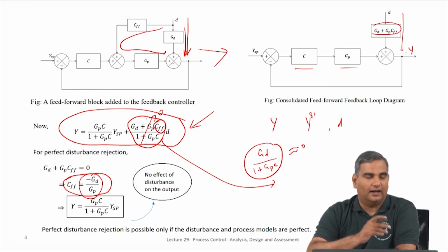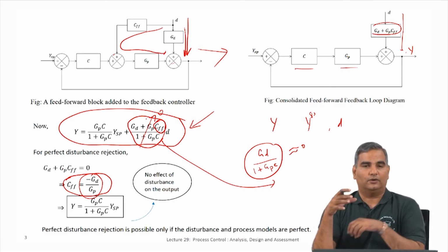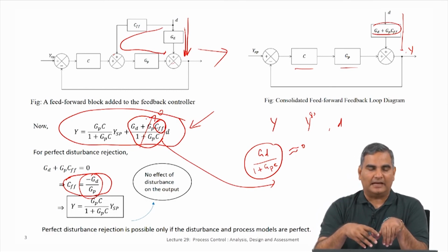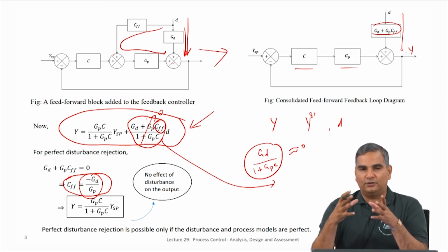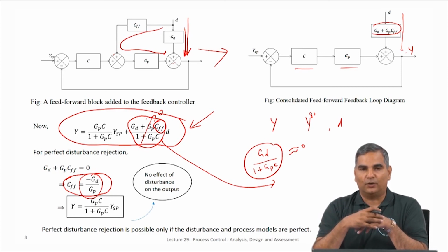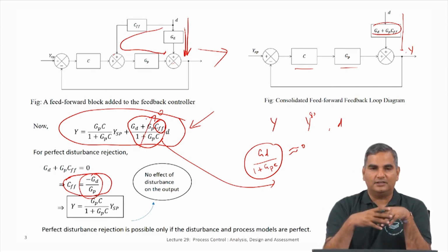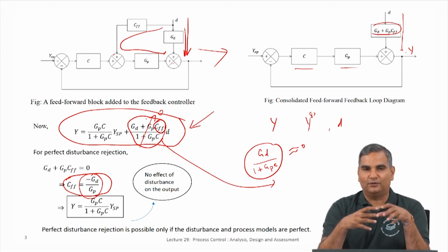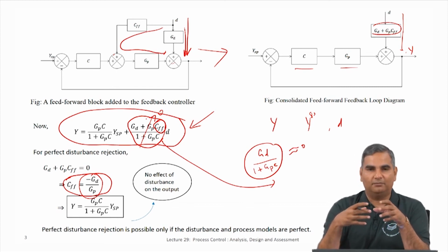That is going to be a logical extension of this feed forward controller, which is called a decoupling controller, and that is the first time we are going to actually look at linear multivariable systems and use some of these ideas to reduce that linear multivariable system to decoupled single input single output systems. In that way we are logically going from the basic closed loop to adding more texture and structure to this closed loop using more blocks based on information.